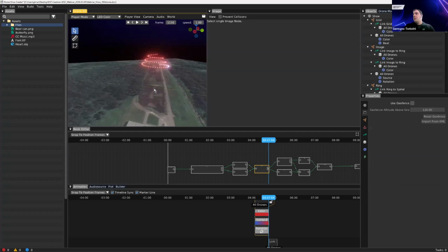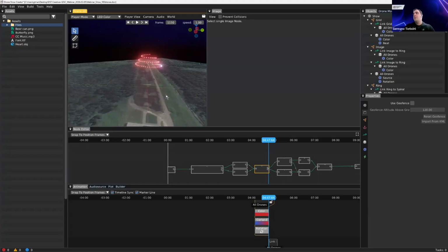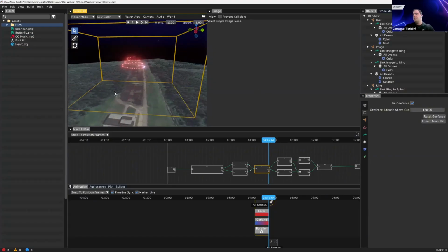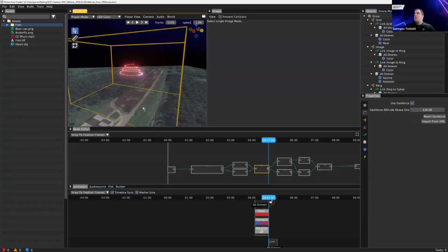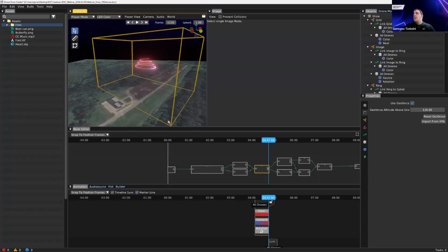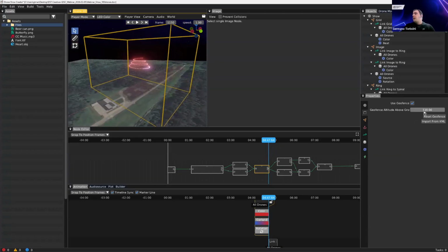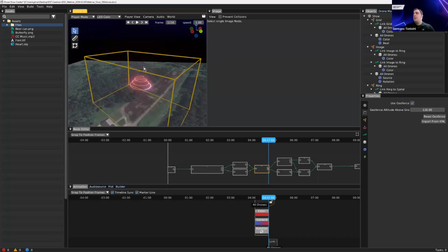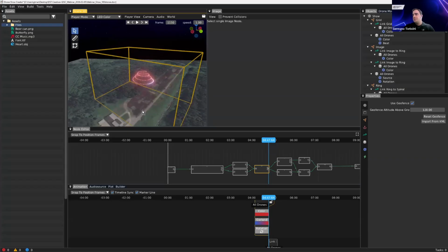And another thing, if you were at our safety webinar about a month and a half ago, you will have heard until exhaustion about the geofence. Here we can also turn on the fence. I've set this one beforehand as well. And I've set its height to 120 meters, which is as high as we can go in most jurisdictions. That's for our dear American listeners around 400 feet.